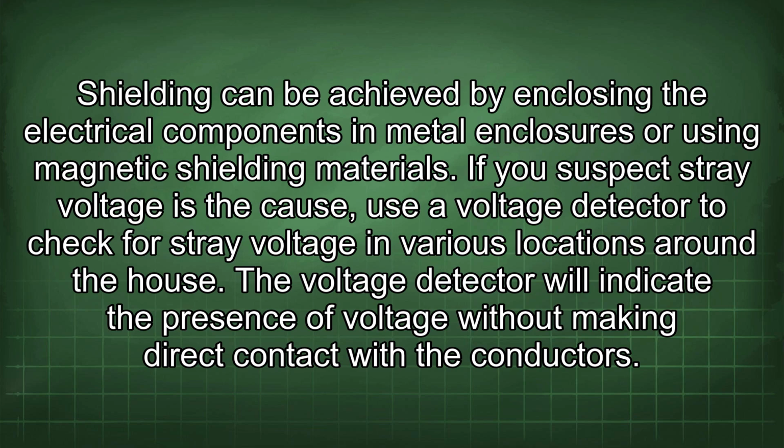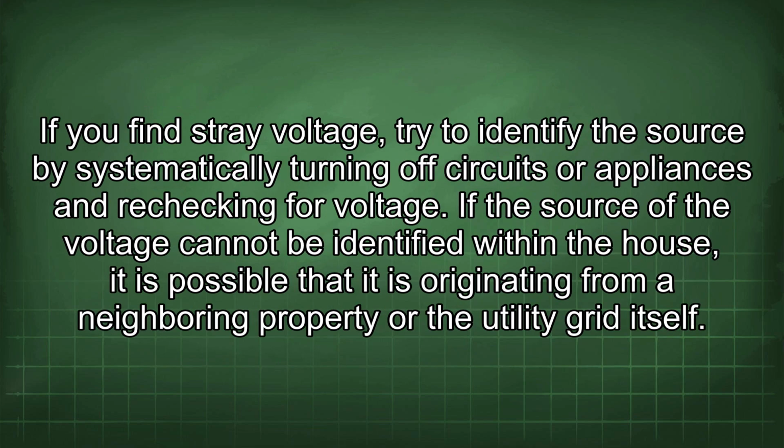If you suspect stray voltage is the cause, use a voltage detector to check for stray voltage in various locations around the house. The voltage detector will indicate the presence of voltage without making direct contact with the conductors. If you find stray voltage, try to identify the source by systematically turning off circuits or appliances and rechecking for